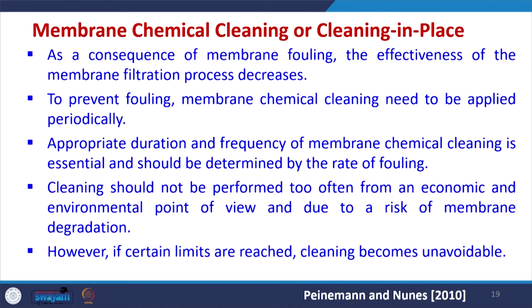Membrane chemical cleaning: as a consequence of membrane fouling, the effectiveness of the membrane filtration process decreases. So, to prevent fouling, some chemical cleaning may be done. The appropriate duration and frequency of chemical cleaning is essential, and it will depend upon the rate of fouling or the rate of deposition of the cake.